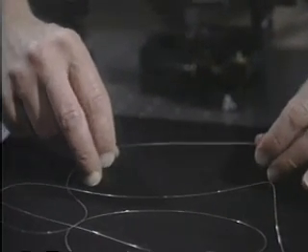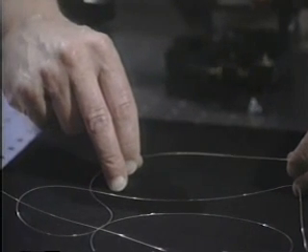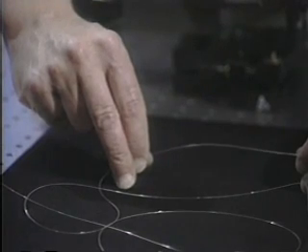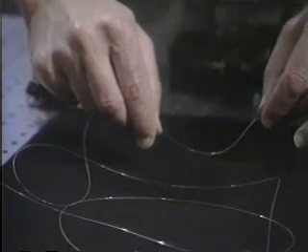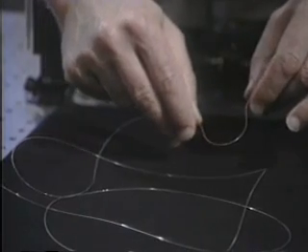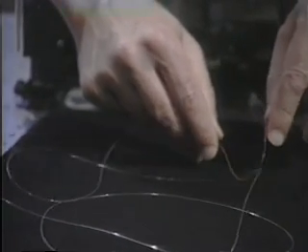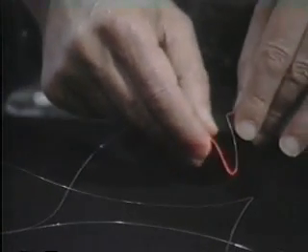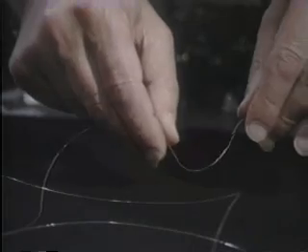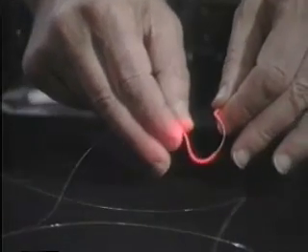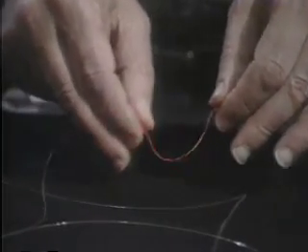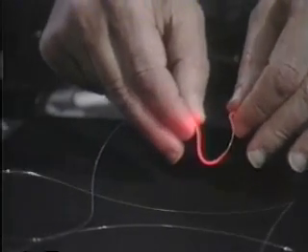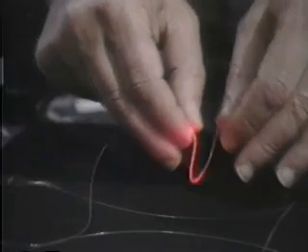Now here's a piece of fiber, and you can see that there's no light scattered from the fiber. Now all I have to do is bend the fiber, and you're beginning to see the light that gets transmitted out of the fiber, kicked out of the fiber because of the bend. The reason is that you start going against the rules of propagation of light in a fiber.